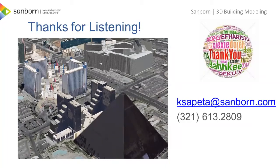Hopefully that makes sense. So the first phase is hydro flattening and creating a contour type model where you remove things like a large bridge, but you wouldn't remove a culvert. And then you have the enforcement of the model where you're digging out your culverts. And then you can also see where water might go in and out of the ground, and you're linking up that whole water system model. You use that for lots of FEMA flood modeling and whatnot. And hopefully that answers the question.